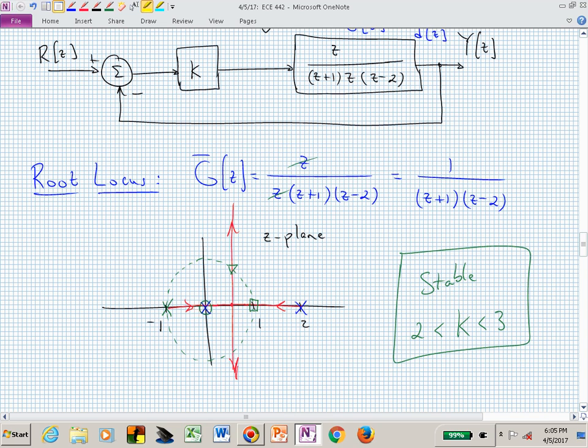Pardon? So the reason is explained in the controller design overview lecture for not canceling poles and zeros outside the unit circle. That's in the supplements to Unit 5, but in short, it basically will lead to unstable or unbounded signals inside your block diagram or inside your system. Maybe not between the reference input R and the output Y, but maybe between the reference input and the input to the system, or the disturbance input and the output, etc. You might have an unbounded signal existing in your system.